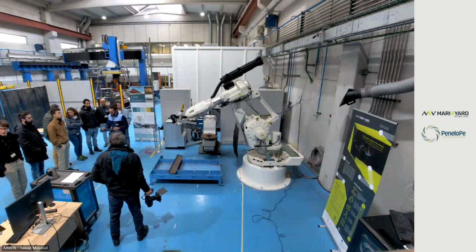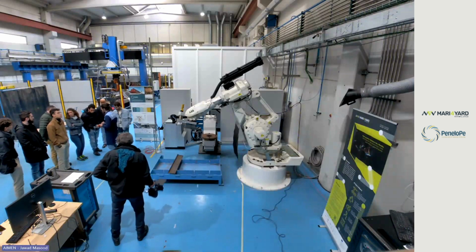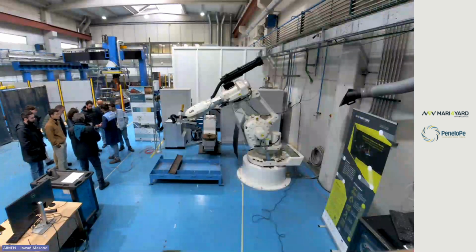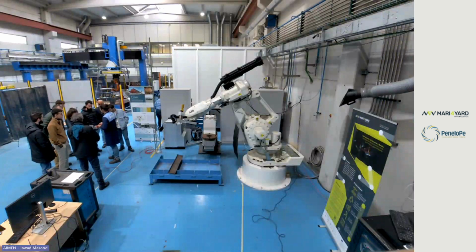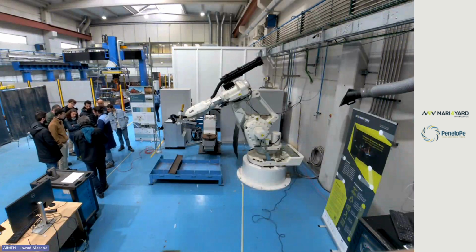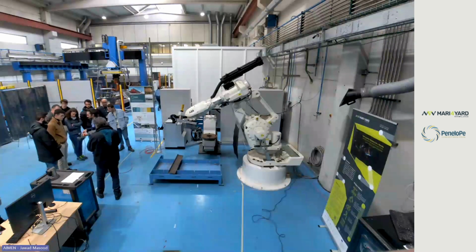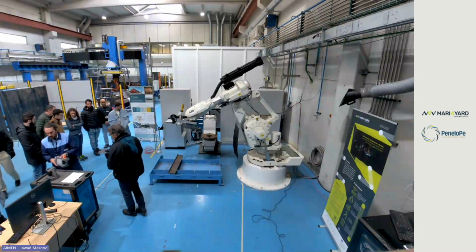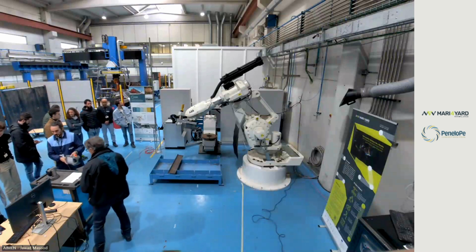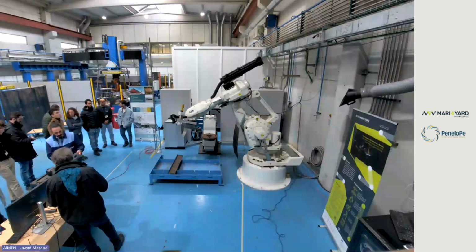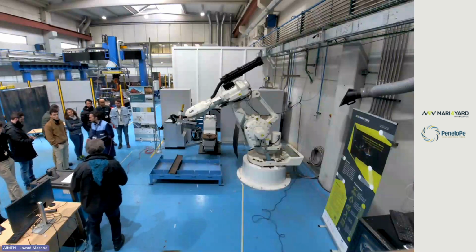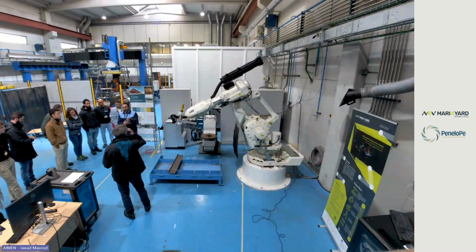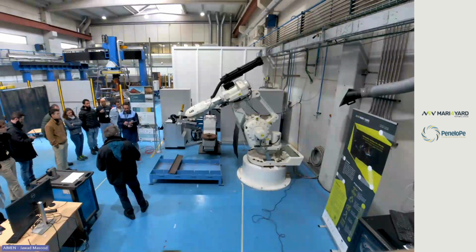What I have here is an instruction with a data position with the name of P home, and the speed, the accuracy we want the robot to achieve, and so on. Now I'm going to save a good position for the home position. I start to move the robot with the joystick.